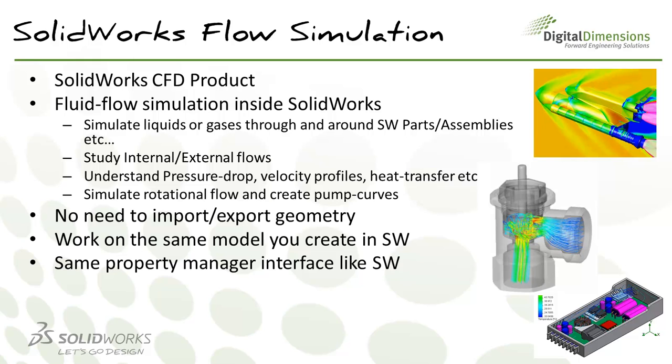So today we're going to be focusing on our CFD product, SolidWorks Flow Simulation. Like I mentioned earlier, it focuses on fluid characteristics inside or outside of your SolidWorks products. More specifically, we can simulate liquids or gases through and around these SolidWorks parts and assemblies. In the following examples, we're going to understand pressure drop with a specific assembly. We're also going to look at velocity profiles, and potentially heat transfer characteristics in your design.